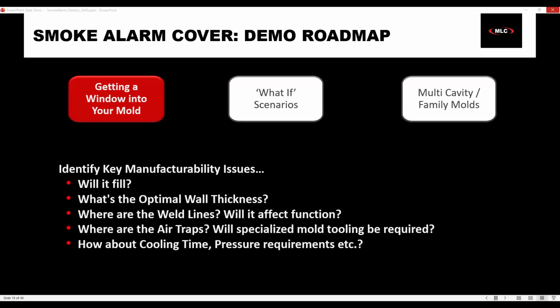Now, there are some other parameters here. Some of this information, such as under general, is not necessarily here. This is something we would need to input. So this is the clamp force limit of your machine. That would be something you would know and want to input there, so we know not to exceed that. And then ambient temperature for cooling. I think 30 is a little bit high. Maybe not in Arizona, take that back. I think it's usually like 25 is 75 degrees, and it's just never that cool here. So that's an Arizona temperature. So there's a couple of different items there.